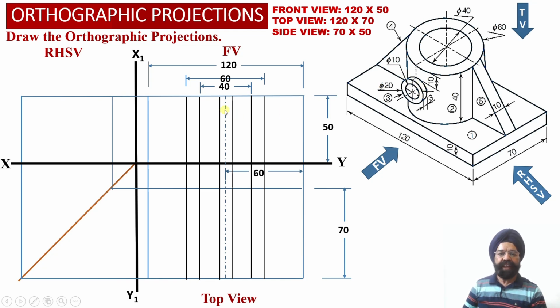So this way now we have to take an offset of 5 millimeter onto the left side and an offset of 5 millimeter on the right, so that these two end points of the short cylinder can be located into the front view orthographic projections over here. Similarly, corresponding to the outer diameter of this short cylindrical element, we have diameter equal to 20 millimeter.